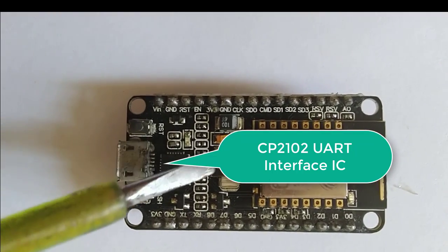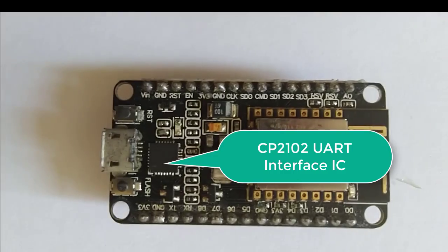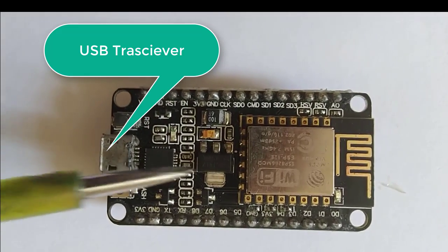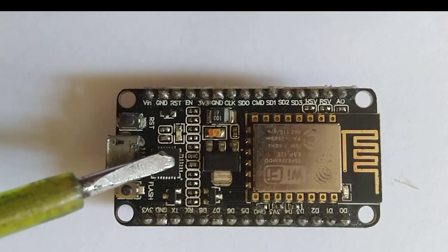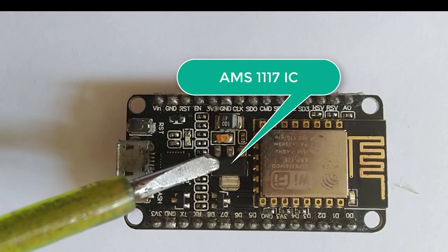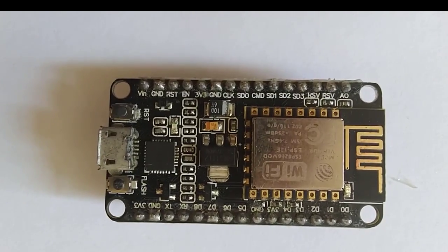And here we are seeing a single chip USB to UART interface bridge, and its IC number is CP2102. It has an integrated USB transceiver, and it doesn't need any external resistors. It also has an integrated clock, so that's why no external crystal is required. An on-chip reset circuit is also there, and it also has a 3.3 volt output voltage regulator, AMS1117. This UART supports baud rates from 300 bits per second up to 1 Mbps.